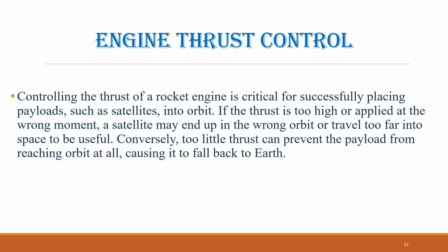Engineers also manage the burn rate of solid propellants by carefully designing the shape of the hollow core that runs through the propellant. Many cores are star-shaped. Initially, the large surface area allows a rapid burn and high thrust. As the star points burn away, the surface area decreases, reducing the rate of combustion and temporarily lowering thrust. The Space Shuttle used this technique to minimize vibrations during the early stages of its ascent into orbit.